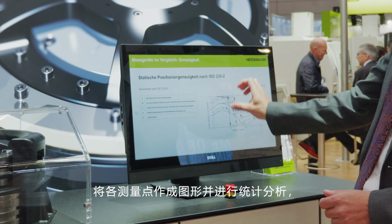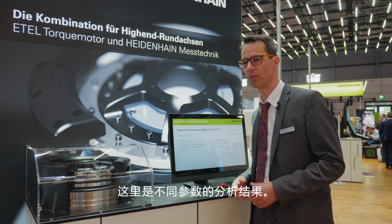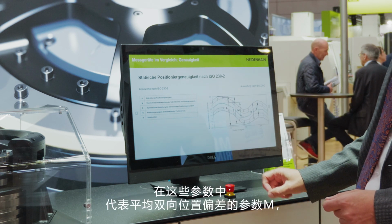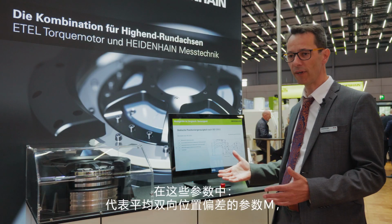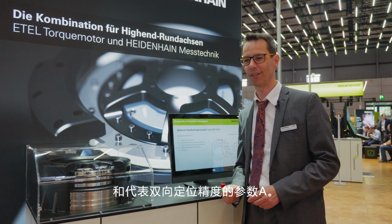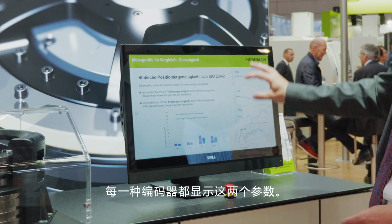The measured points are plotted, and a statistical analysis is performed, yielding the various parameters listed here. These include parameter M, the mean bidirectional positional deviation, and parameter A, the bidirectional accuracy of positioning. Both are displayed for each encoder.